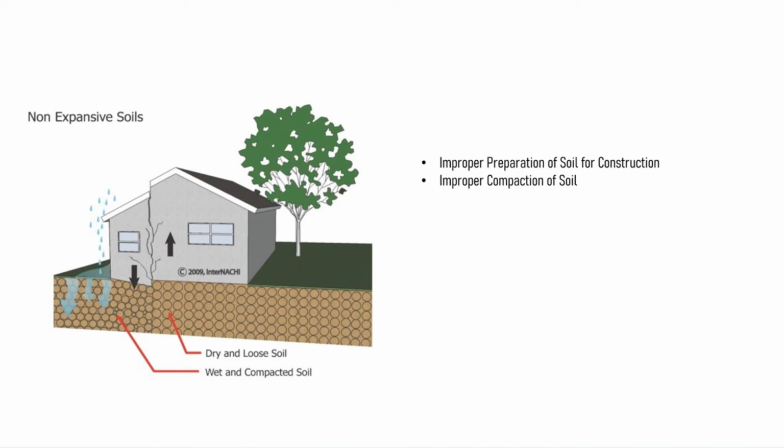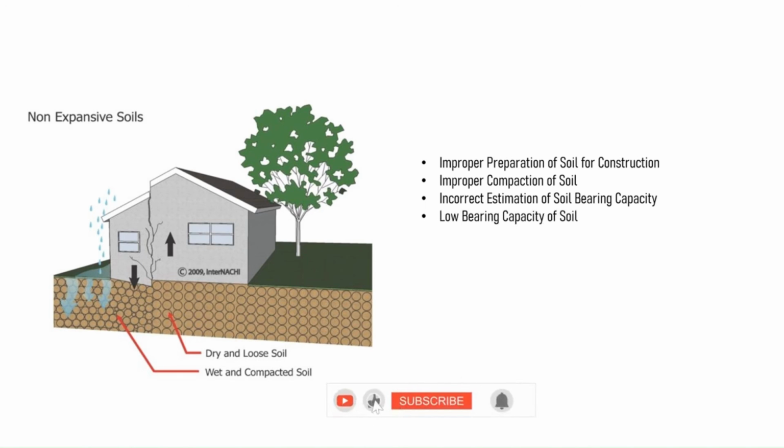3. Incorrect estimation of soil bearing capacity. To what extent a particular soil requires preparation is dependent on the current soil bearing capacity. A wrong estimation of soil bearing capacity results in error in the proper preparation of soil, which causes foundation settlement. 4. Low bearing capacity of soil. Lower the bearing capacity of the soil, the higher the chances for foundation settlement, irrespective of what causes a low value of bearing capacity.